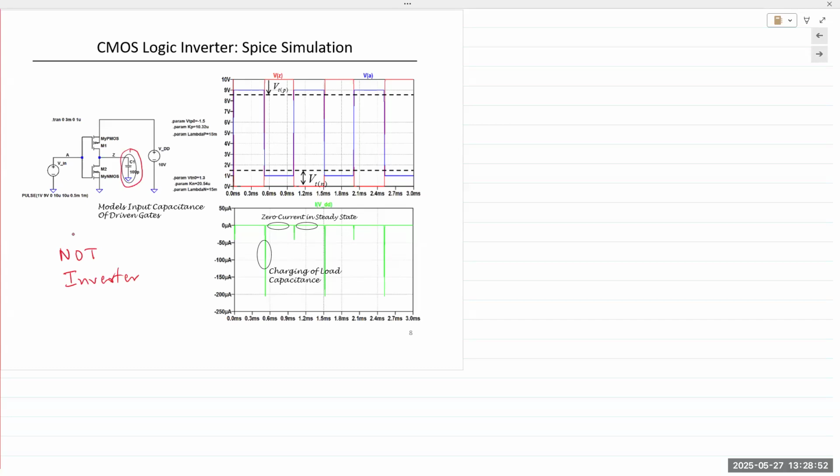Remember, at the input of every MOS device is a capacitor, right? So the assumption is that we are going to connect these in cascading circuits. And so instead of a resistor, we attach a capacitor at the output to simulate the capacitance of the gates that are going to follow on. A 0.1 nanofarad capacitor at the output is enough to simulate the follow-on logic gates.